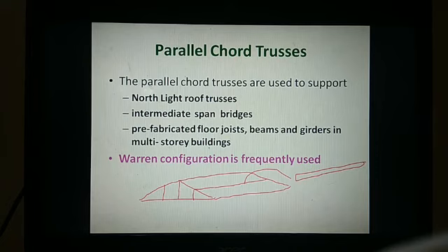What do you mean by bay? Bay is nothing but the distance between two roof trusses, isn't it? So when the bay length is more, even the normal angular section, C section and I sections can't be accommodated. Then you have to go with another truss to connect these two main trusses. So this truss can be used as a parallel top chord truss like this.